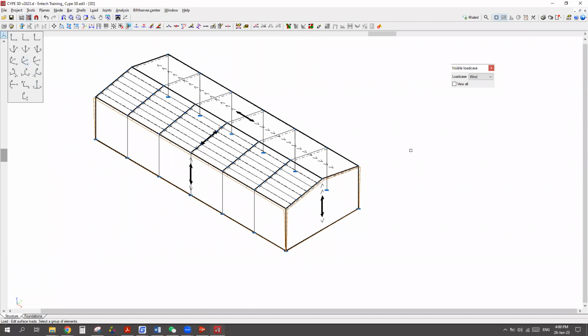Do you have any questions so far? Self-weight will be calculated automatically, so you don't need to worry about that. It's not like STAAD.Pro. You just need to look at the superimposed dead load, superimposed live load, and other types of load that you have: wind load, earthquake load, soil pressure, whatever you have. Forget about the self-weight because it will be calculated automatically. Any other question?